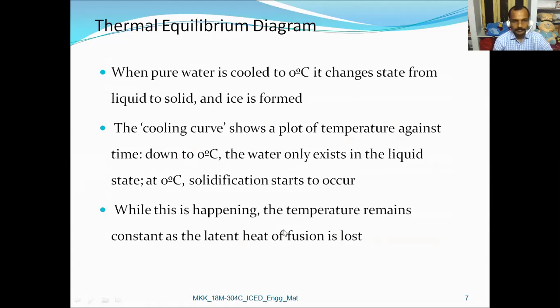The cooling curve is a plot or graph generated between temperature and time. Whenever the temperature of the water is reduced to 0 degrees centigrade, where the water only exists in the liquid state, at 0 degrees centigrade solidification starts. While the process is going on, the temperature remains constant as the latent heat of fusion is lost.